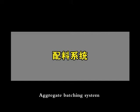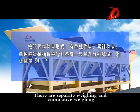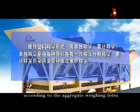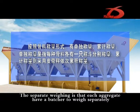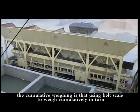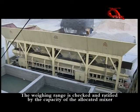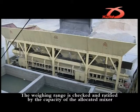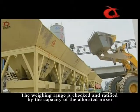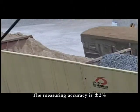Aggregate batching system. Weighing may be done in accumulated or separate modes, according to the operational form. The separate weighing occurs when each aggregate has a batcher to weigh separately. The accumulative weighing uses a belt scale to weigh in shifts. The weighing range is checked and adjusted according to the capacity of the allocated mixer, with measuring accuracy allowing for a plus or minus 2% error.